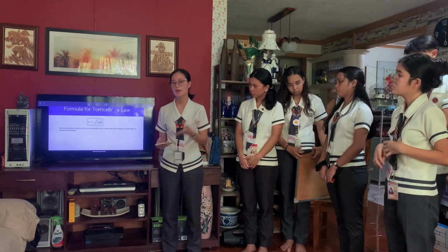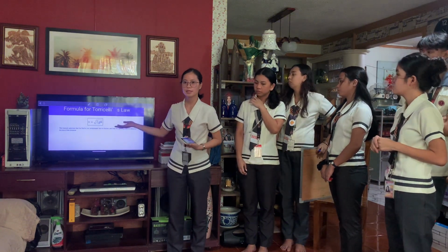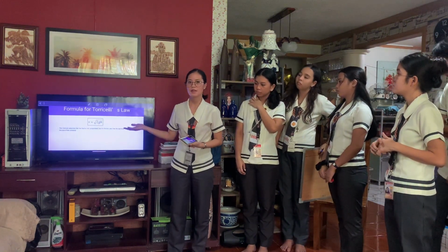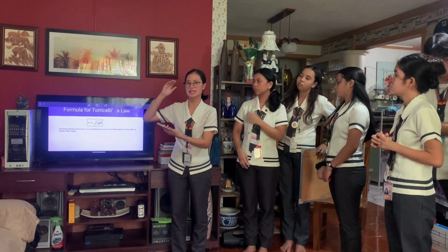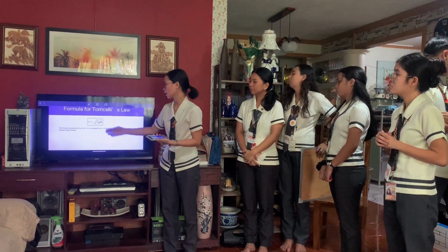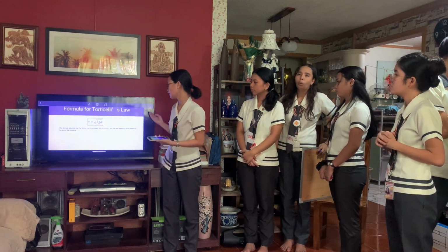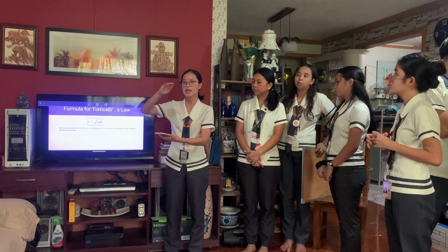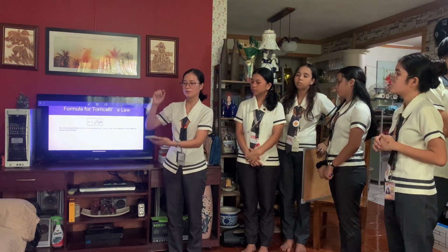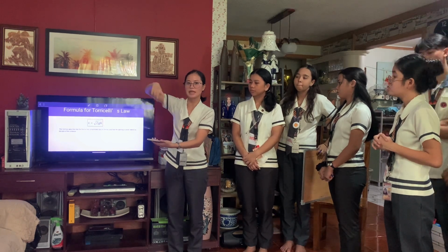However, remember that this formula will only be used if the liquid in the container is an ideal fluid. An ideal fluid is not compressible, has no friction, and the opening is small relative to the size of the container.